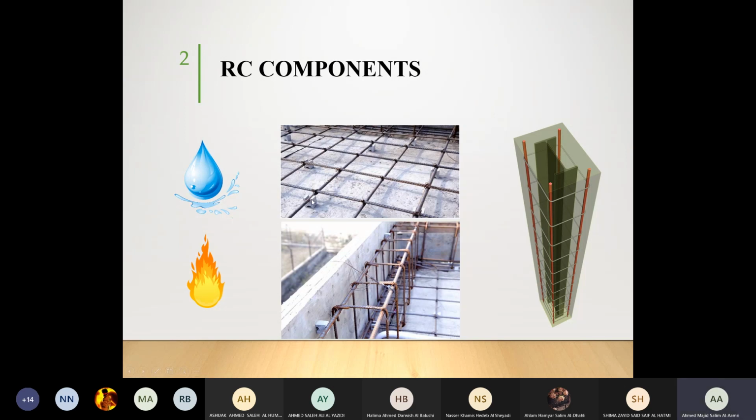So what you have done for cover, you have put certain elements. Cover is normally from concrete, so you have applied certain elements which will not be affected by water. After that, you supplied your steel, so water will not penetrate to your steel bars unless there are cracks inside. Okay, so the proper solution to avoid any corrosion is to apply proper cover. Can you see the cover here in case of the slab and in case of the beam here? Can you see these covers?